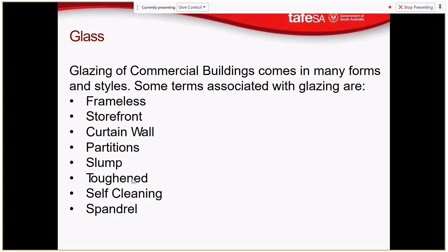But the more modern way of doing that in laminated glass is to have, I think, a polyethylene film, a clear film that goes between the two layers of glass, and I think it doesn't need to be heated up again. You've got your glass, your film, and another piece of glass on top, and when you go to break that glass, the polyethylene film stops it from breaking through. It'll still break into pointy shards like standard float glass, but you won't be able to break through it because it's quite tough. It's flexible, it will stretch.